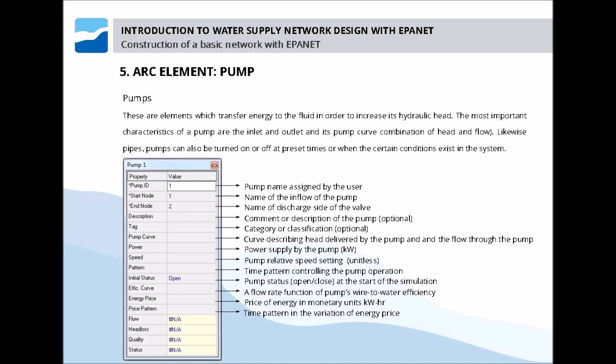Additionally, it is worth mentioning that EPANET can take into consideration energy consumption and the cost of the pump. Every pump can have an efficiency curve and an energy price list assigned, and the current slide shows all the pump elements we can see in the data model.